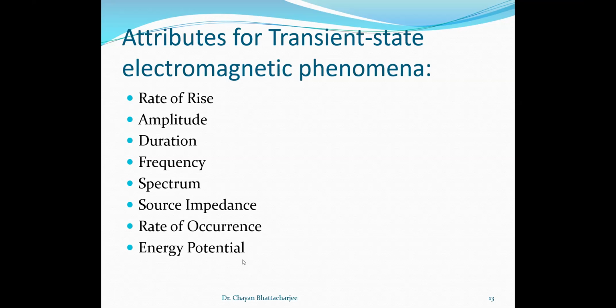Higher impact, what am I hinting at? I'm hinting at the fault level current. So the greater the voltage difference in that lightning strike, the higher the injected current in the transmission lines. The fault level current will increase, and so will the chances of a disastrous fault. Not just a fault, it means all three phase faults. It can be a 3LG type or a DLG type fault. So the interruptions will be severe.